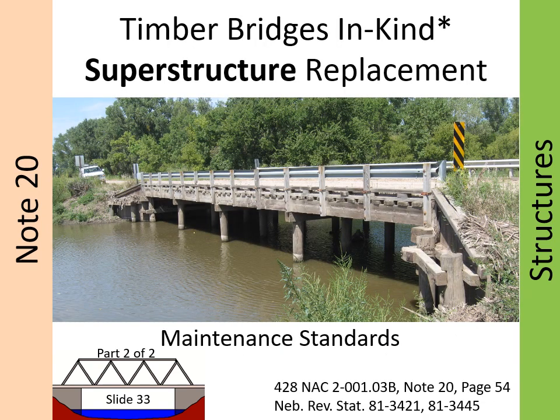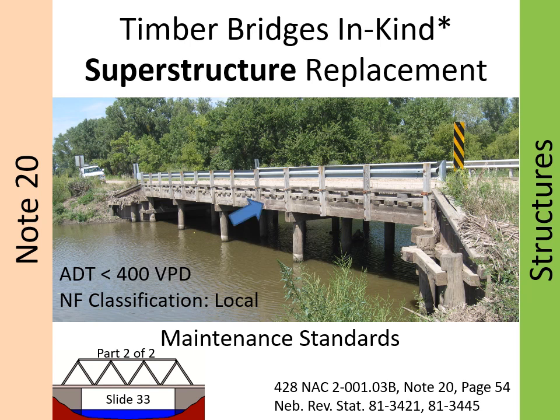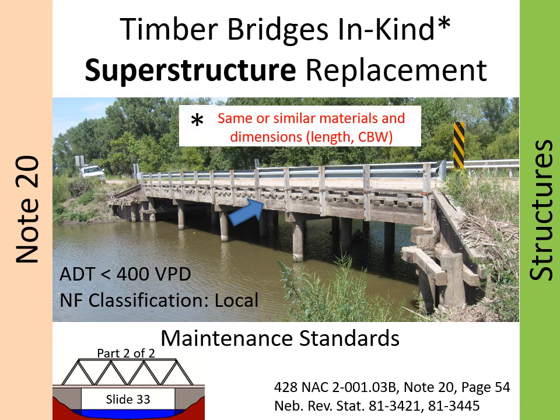Note 20 on page 54 of the standards provides that a timber bridge under certain conditions can have its superstructure replaced in kind under maintenance standards. The conditions are that the National Functional Classification is local and the ADT, or traffic volume, is fewer than 400 vehicles per day. A superstructure is the portion of the bridge that supports the deck and is supported by the substructure. In kind means using the same or similar materials and building to the same dimensions, length, and clear bridge width. A reminder, replacing in kind may involve the practice of engineering.